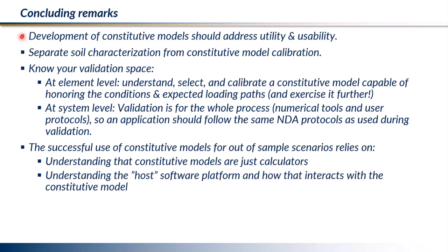So my concluding remarks go back into basically every one of my sections today. Development of constitutive models needs to address utility and usability. We did that with the input parameters and the generalized calibration against what we know from the field. It's always a good idea to separate soil characterization from soil calibration. Understanding the validation space, the loading paths that you expect, how your model will respond to those, what is going to get activated, and go into that loop of checking the element, going to the system and back. And then being able to successfully use such constitutive models.